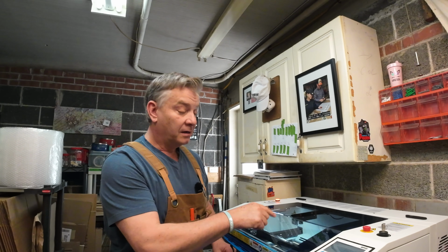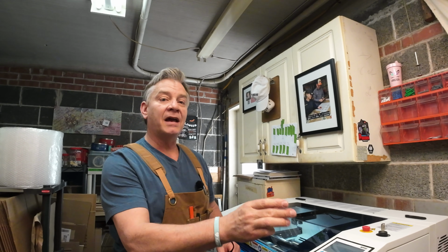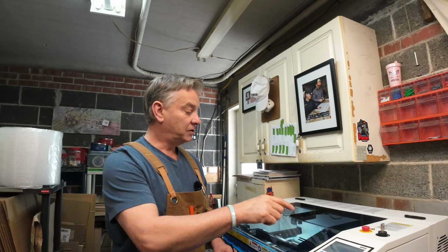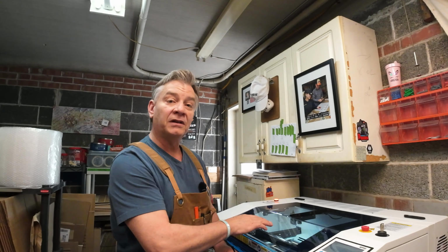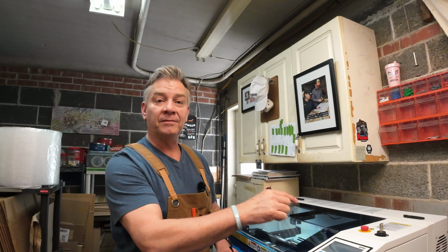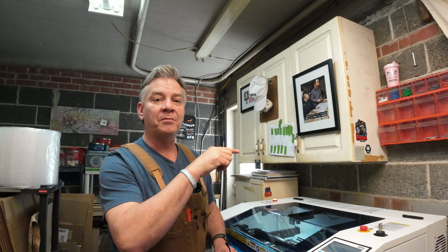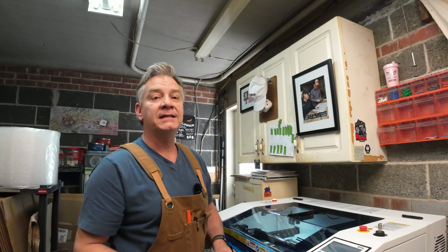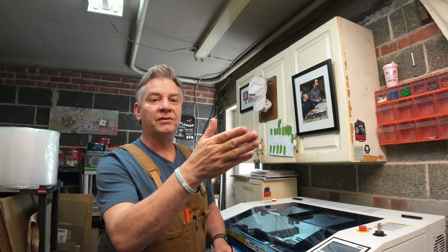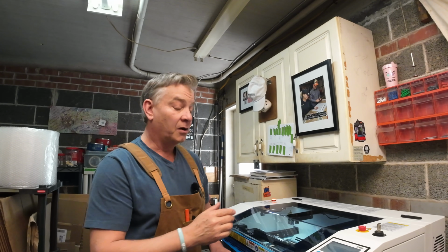In other words, it's user defined. That green dot is the tie that binds my design to wherever it is I choose to put the laser head and press origin. That connects it. It says that's where the green dot is. This is where the design begins relative to where I set it. Whether it was the top left corner, top right, doesn't matter. It'll work it from there.